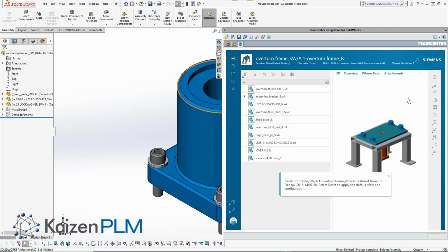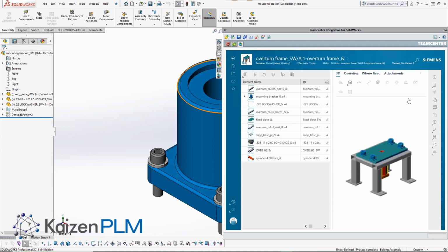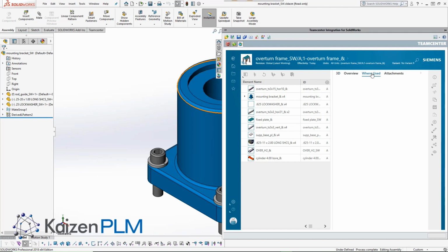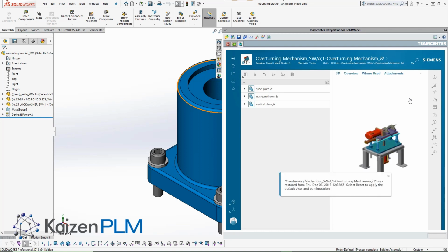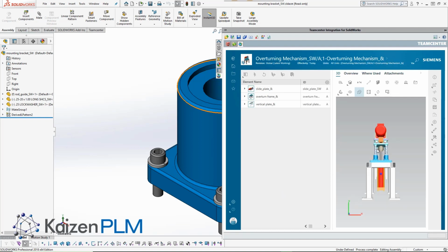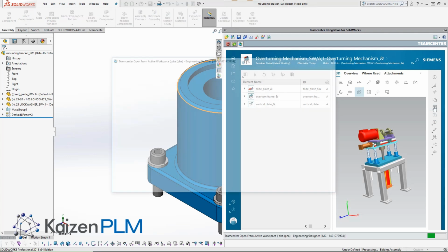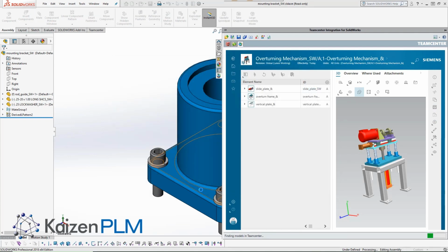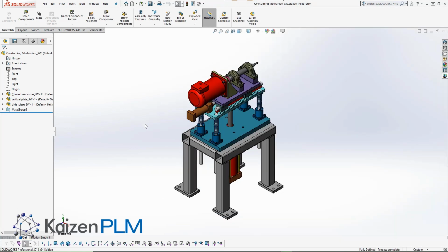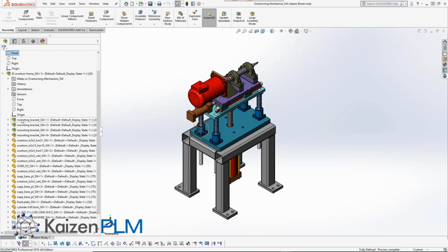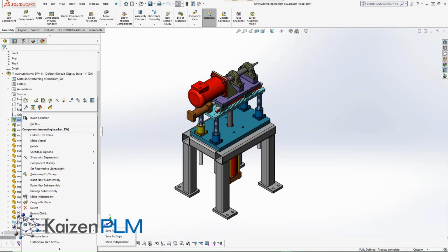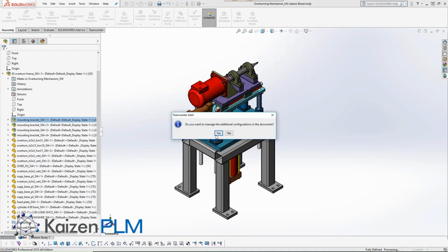The designer performs a where-used search in Teamcenter, to find and load the top-level assembly into session, so that it is automatically modified as the target design changes. Now that all required models are available in the SolidWorks session, the subassembly may be copied. The user has the choice to create an independent copy, a replacement copy, or an occurrence-specific replacement copy. In this case, he will replace both occurrences of the subassembly with its copy.